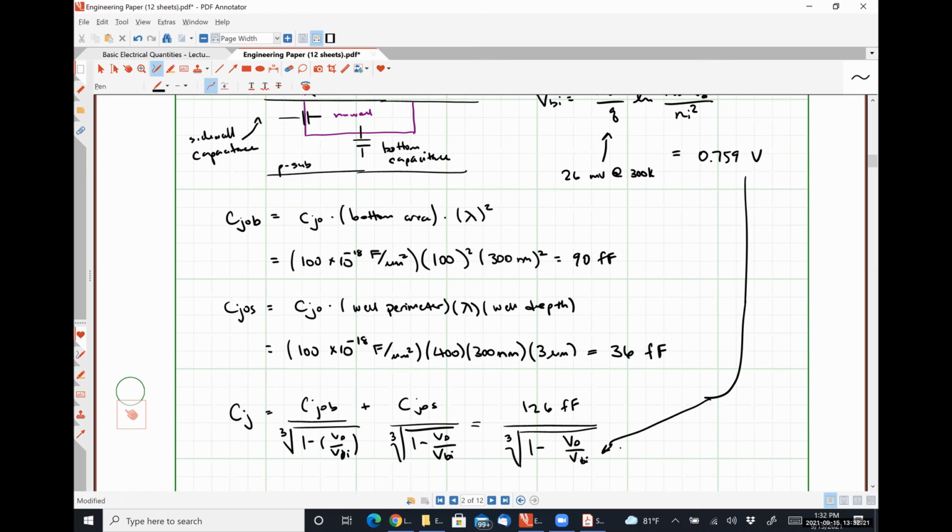And then when we talk about a couple of other layers, we'll talk about how they can be used as resistors and how they avoid this. But those other layers are not common to effectively every CMOS process, and the N-well is. So if you're building a simple analog device, not 5 metal layers, not 2 poly layers and all this kind of stuff, this is all you've got. So it's reasonable to actually cover it instead of saying you can do better by doing X.